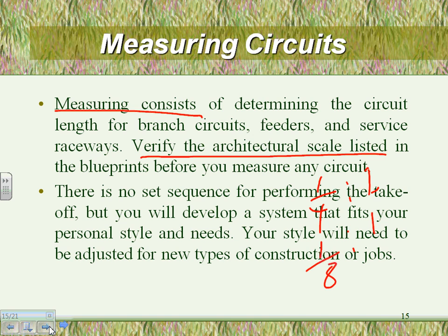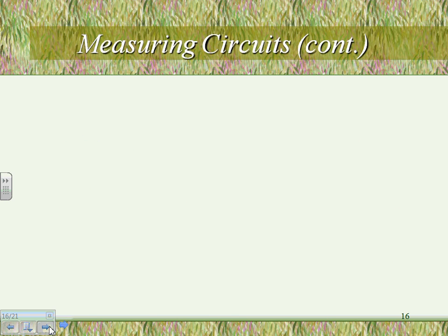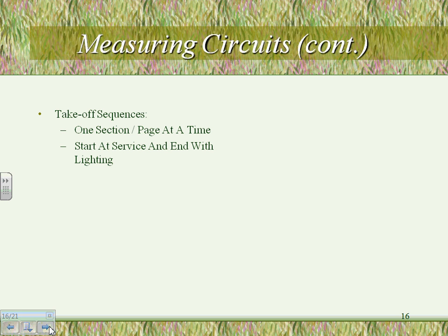The question is, when I start the takeoff, where should I start with the takeoff, guys? It doesn't matter as long as you have a system. The idea is to have a system. Here's a couple of suggestions for takeoff. What we did with me, when we did them by system, is we do the lights first, then the power, then the low voltage. Here's one takeoff sequence.